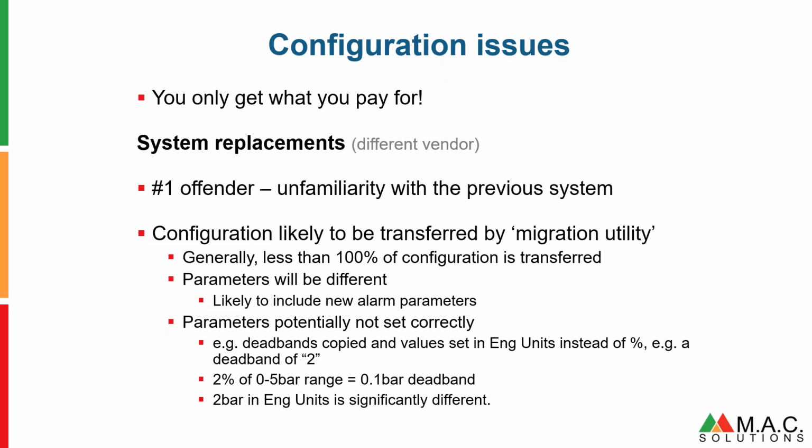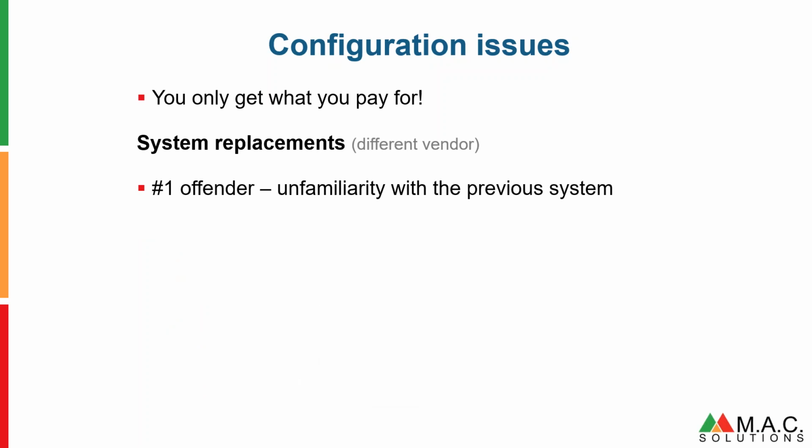The system was cluttered up with standing alarms. The alarms never cleared, went into condition, and this was done by a migration utility, by people who didn't understand what the old system did. Therefore, they just blindly copied values, and that caused all sorts of alarm problems. All the things that were set by default, hundreds of new alarms that they didn't want, including the return to normal alarm. So think about what you're getting.